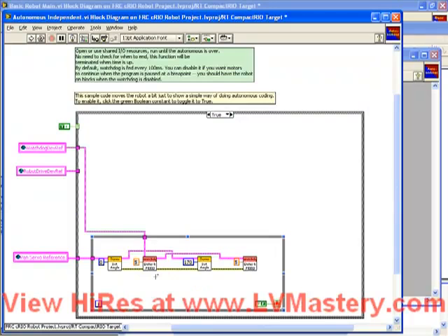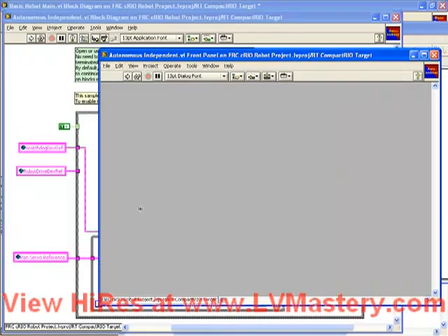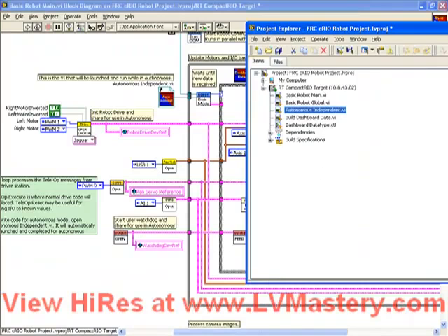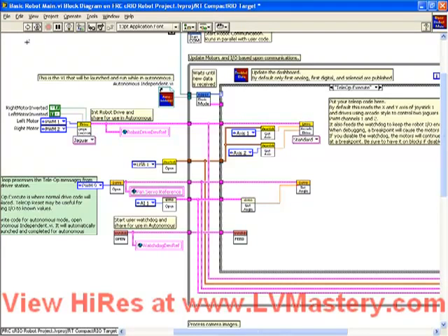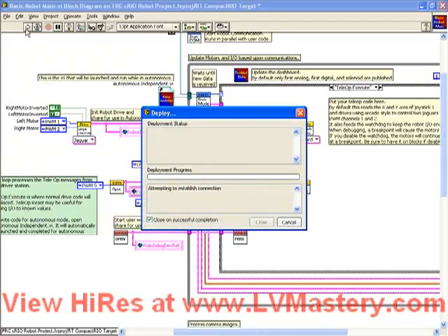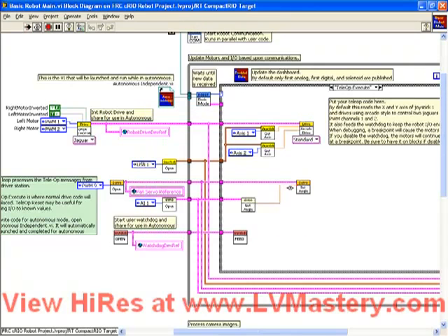So then all you need to do is save and close this VI, and then run the robot main to deploy it. It may ask you to save changes. Once you do so, it will deploy. And then once it's running, you can probe to look at your angle in teleop mode, which will also be a nice way to tell you once the robot has actually started and begun executing.